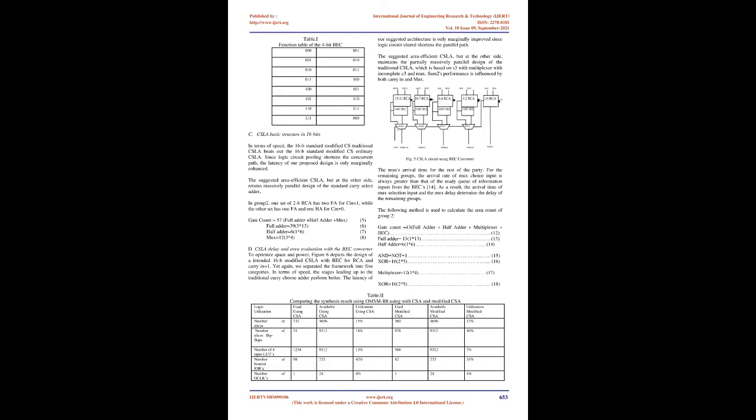The fundamental component of an arithmetic unit is an adder, and a complicated digital signal processing system contains numerous adders. The CSLA is used in many computing systems to reduce carry propagation delay by creating multiple carries independently and then picking one just to produce the aggregate. The architecture of an RCA was straightforward, even though the main issue is delay in carry propagation, CPD. The carry select adder, CSLA, seems to be the fastest of the classic adder architectures.